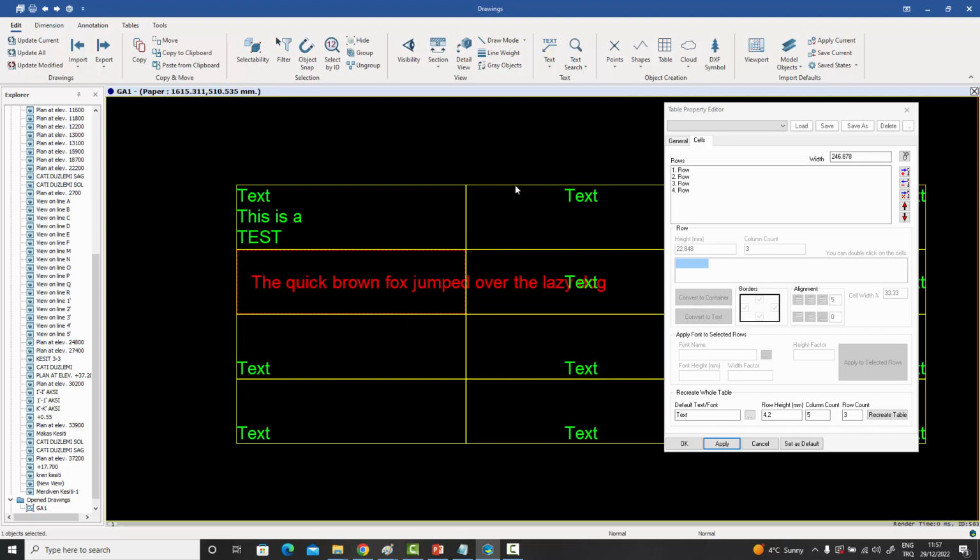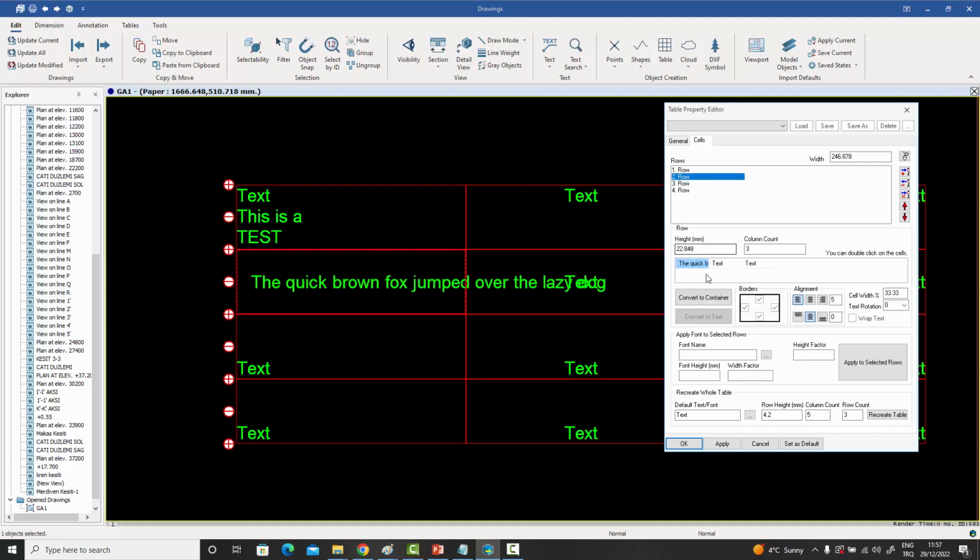So what I can do in that case is select the table, go to the second row, select this text from here, and say wrap text. And when I say wrap text, then that text can be wrapped inside that particular cell, as you can see on the screen. If I come back to this text rotation feature and convert this long wrapped text into a vertical text, for example, by choosing the 90-degree option, you can see that I can even do that, and it now wraps in the other direction. So this is very useful, and you can create lots of different combinations and styles for some very specialized tables which you might have.